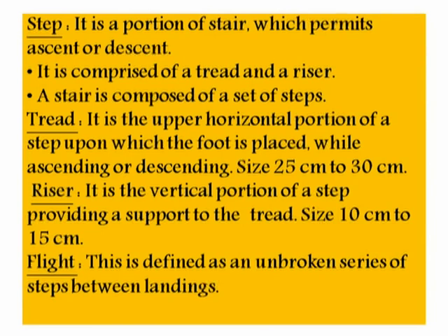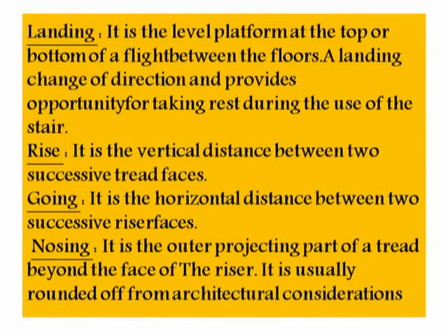Flight. This is defined as an unbroken series of steps between the landings. You see that this stair is not a continuous one. There is some big horizontal space for rest, that is known as a landing. So the complete series of steps is known as one flight. There may be one or two flights for climbing from one floor to another floor, and in between that there is normally a landing provided.